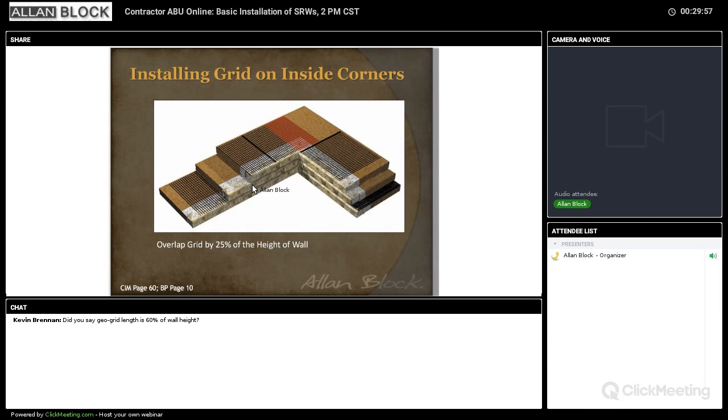And feel free to put more in, but make sure that you fully compact this area back there all the way to the cut if you have a corner back there. Because we have to remember, if you don't compact now, it will self-compact over time, and eventually that will lead to sagging soil above the wall. And you don't want that. You want to compact it very well now, so that there's no settlement over time.